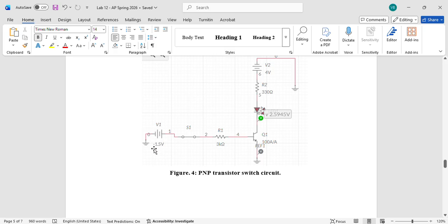So now we can see a negative sign in the voltage. There are two possibilities: either add a negative sign in the voltage, or we can make this battery in the reverse direction. Both are possible, and we will try to see both in our actual Multisim simulation.